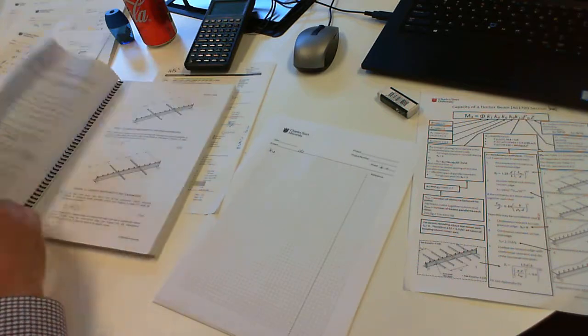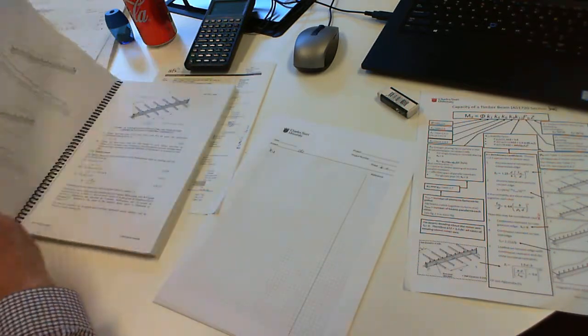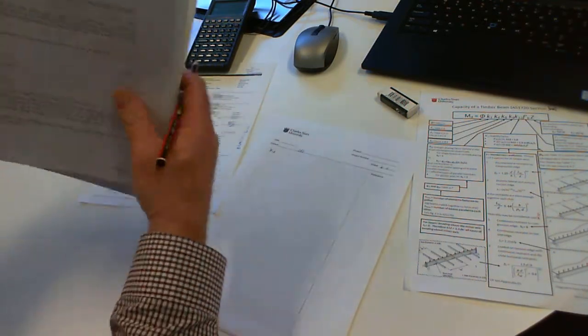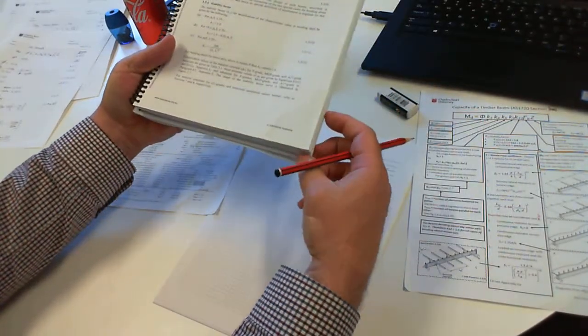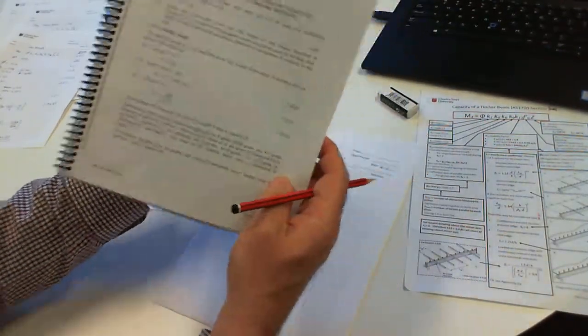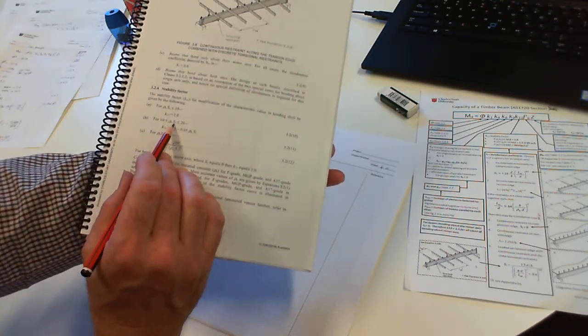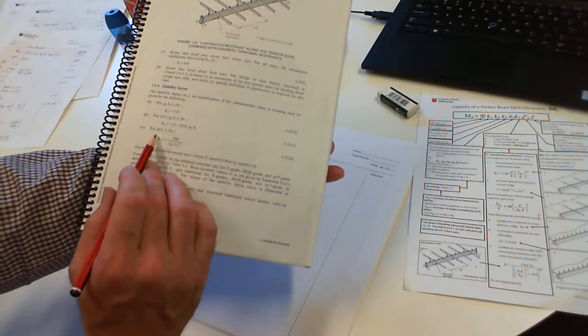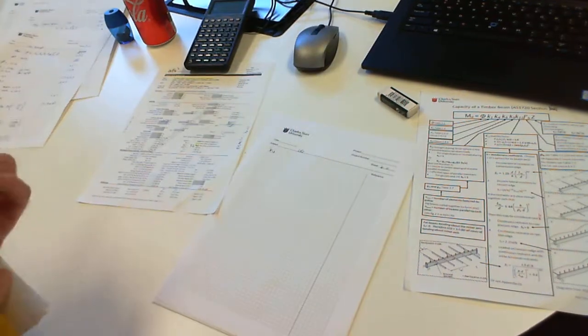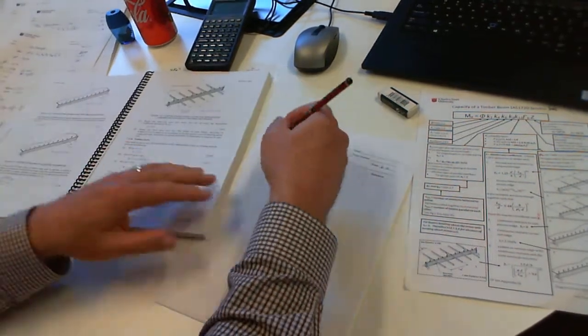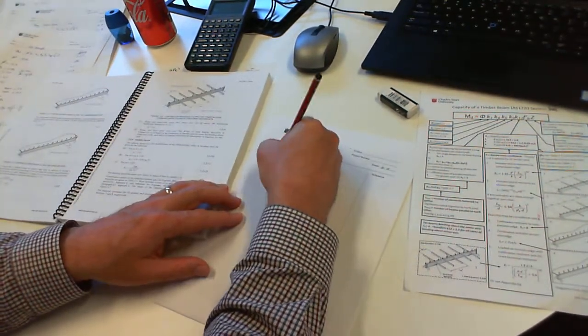K12 comes from clause 3.2.4 of the code, which says if rho b times S1 is less than 10, then K12 is 1. If rho b times S1 is between 10 and 20, there's a formula. If it's over 20, there's another formula. So we need to first find what's rho b.